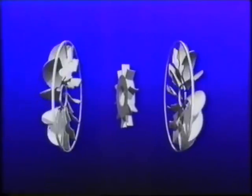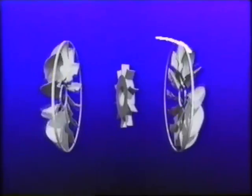As the pump impeller keeps rotating, the turbine runner also rotates and gradually reaches the speed of the pump impeller. When this occurs, the returning fluid hits the back of the stator blades. The stator is now blocking the flow of fluid. To prevent this, the stator is fitted to its shaft via a one-way clutch.